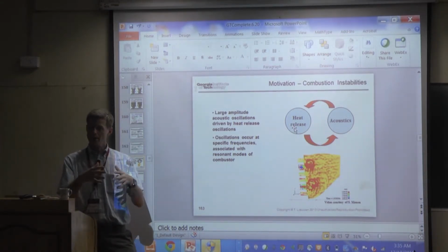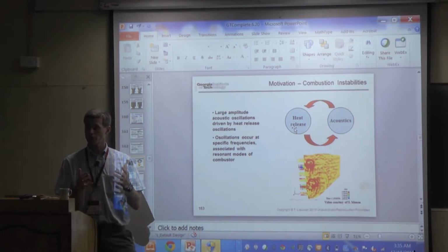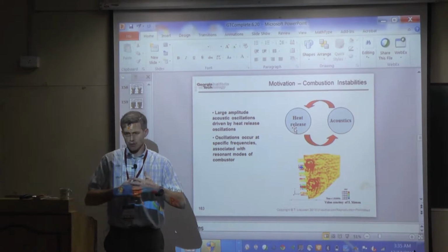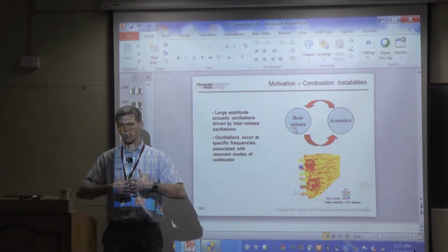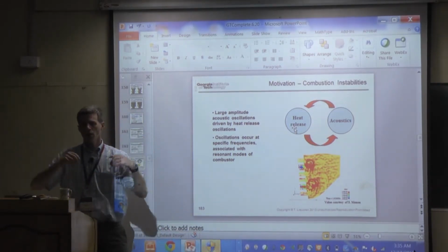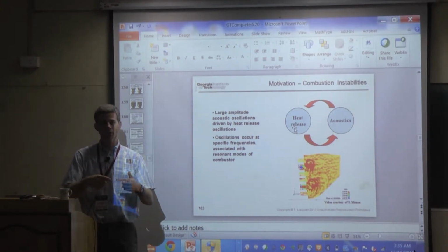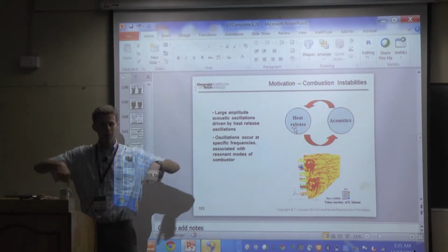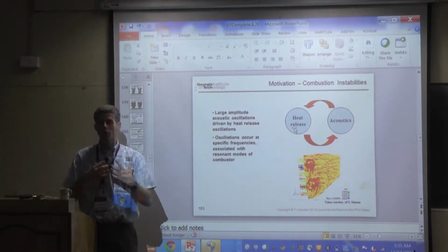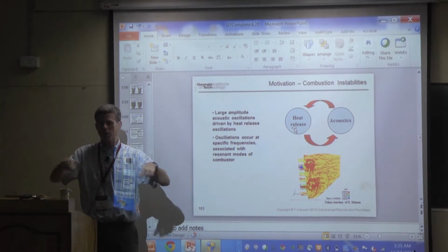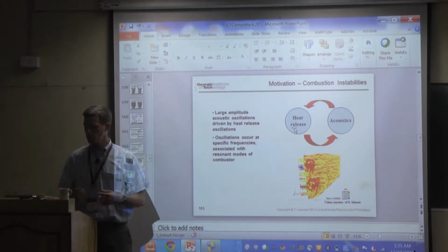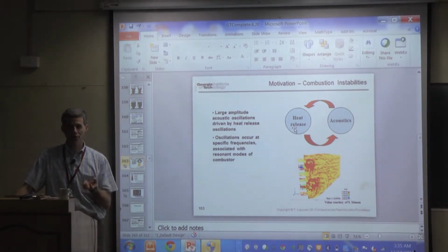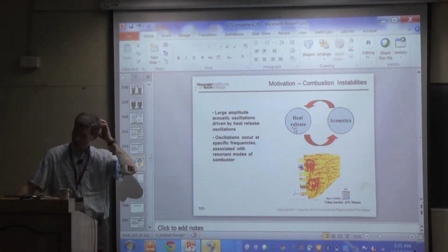But when you take that bass speaker and put it inside an enclosure, inside a cabinet, when the cone moves out, it compresses the air a little bit, and that compression generates a propagating sound wave. When it's not in the enclosure, when the cone moves in one direction, the air that was in front of it simply moves around to the backside, and there's no compression of the air. You're just sloshing the air around. You're imparting some kinetic energy into the flow, but in order to generate sound, you have to cause a little bit of compression.